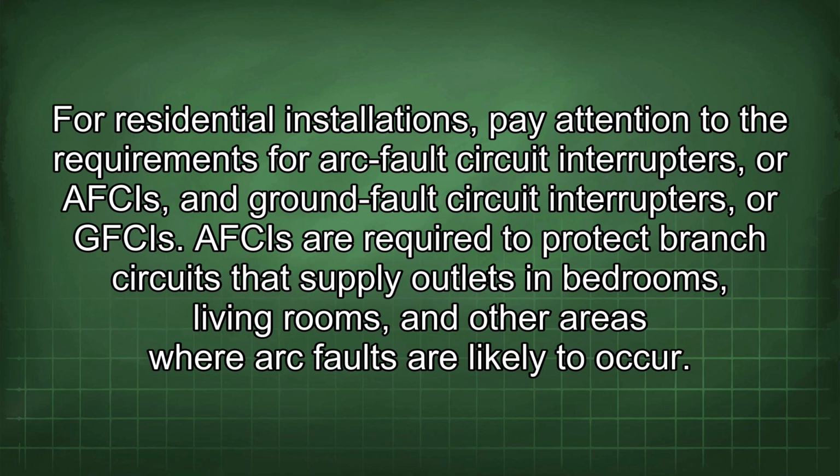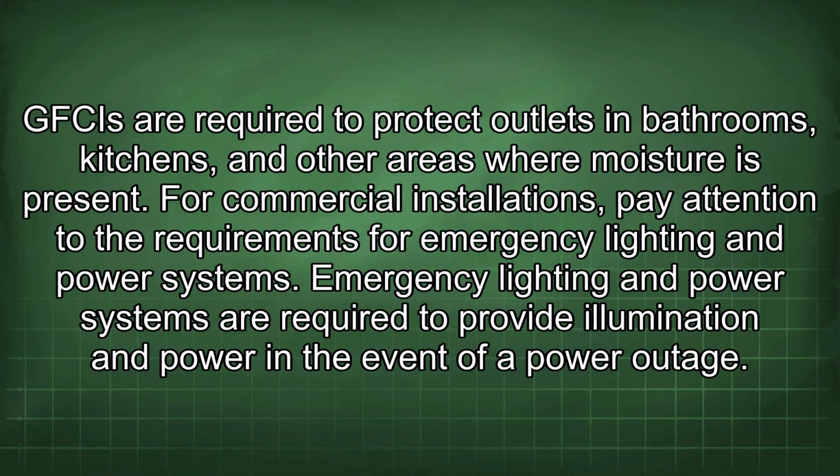For residential installations, pay attention to the requirements for arc fault circuit interrupters, or AFCIs, and ground fault circuit interrupters, or GFCIs. AFCIs are required to protect branch circuits that supply outlets in bedrooms, living rooms, and other areas where arc faults are likely to occur. GFCIs are required to protect outlets in bathrooms, kitchens, and other areas where moisture is present.